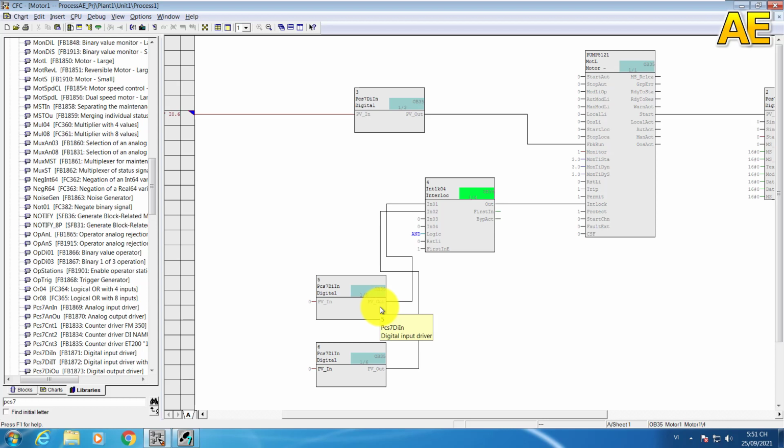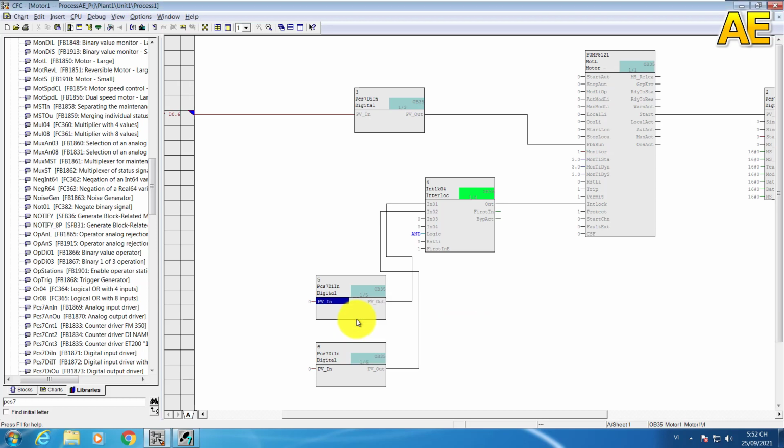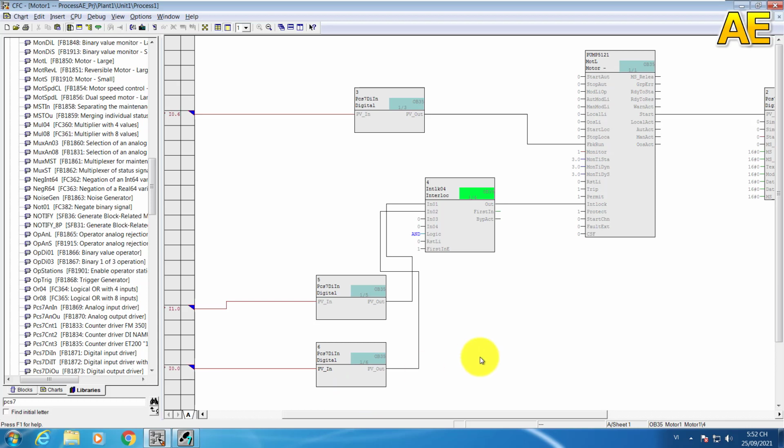Okay, now I will connect the tag to digital input number 1 here. We right click and interconnection to a tag. I will select the level switch high 6101 input. And for the second condition, I will select the valve, the valve 1101 open feedback here. Okay.